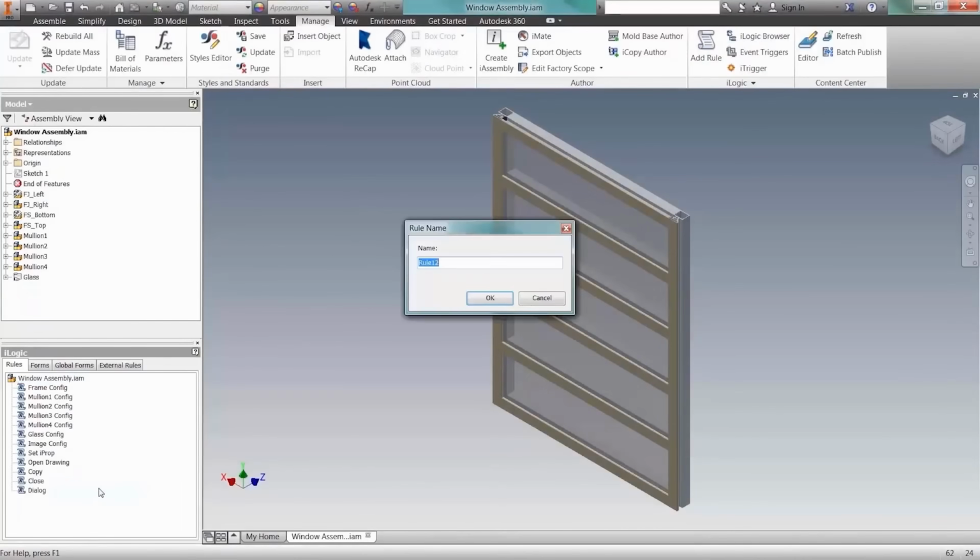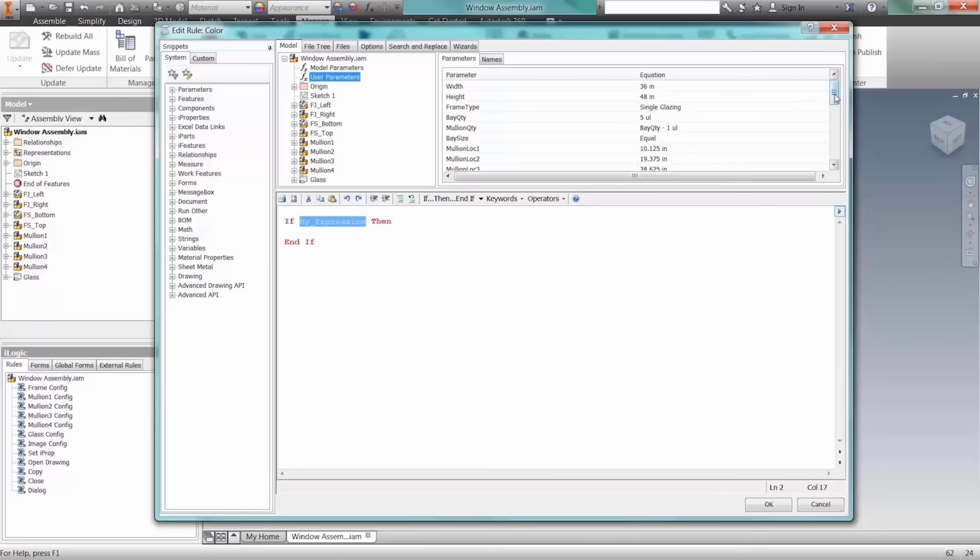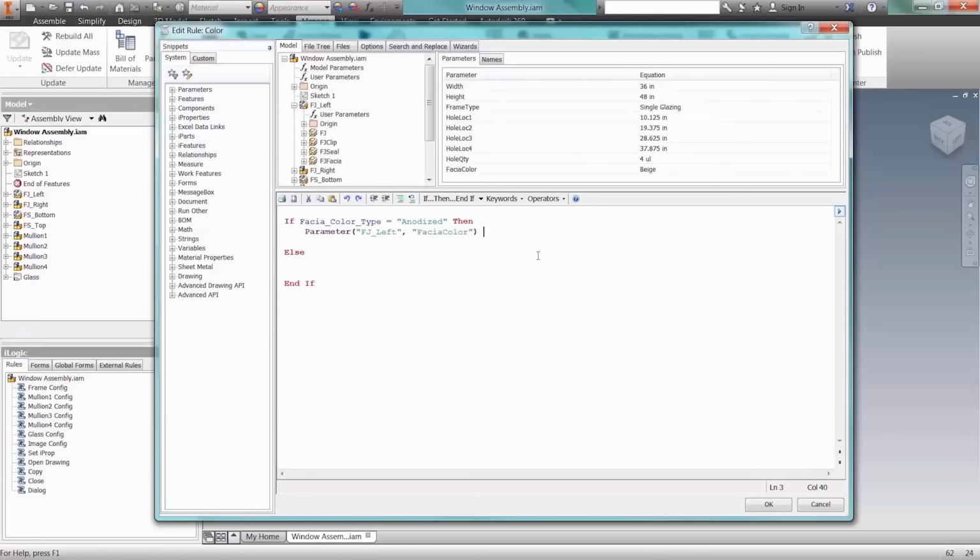But iLogic is essentially custom automation for designs, which really doesn't do it any justice. So with iLogic, you create code snippets to automate almost anything. The creation of drawings. You can automate repetitive tasks in Autodesk Inventor. You can automate metadata creation. You can create visual forms with product configurators and then build, model the design through automation.